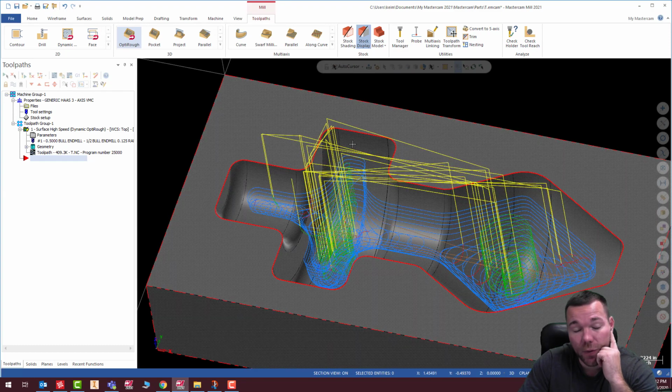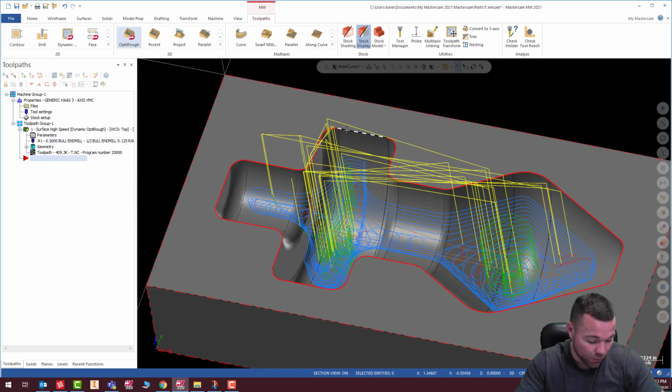thing. Now, the thing to remember here is we have a 1/8 inch radius in the corners of a lot of these, so we want to use a smaller tool, ideally smaller than a 1/4 inch, because a 1/4 inch end mill would perfectly fit into that 1/8 inch radius. So we don't want to have full engagement, a 90-degree engagement on that tool. So what we'll do is we'll probably use a 3/16 ball mill so that we're actually cutting around there. We're actually going around that arc rather than just plunging into it.